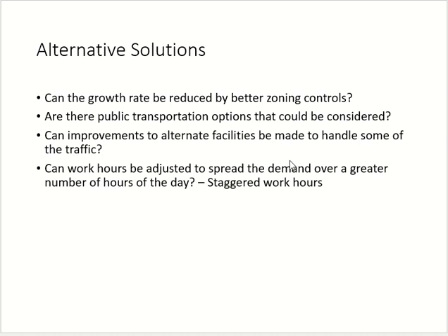What's the reason? So that the traffic is distributed. If you don't do it, in the future those highways which are now looking good will become congested and traffic jams will happen. So they build parallel highways or facilities so that traffic is distributed and volume becomes less.